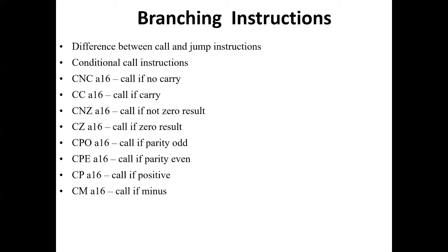Next is CPE A16. CPE is a mnemonic which stands for call if parity even. This instruction is used to branch to the subroutine whose 16-bit address is provided in the instruction only if parity flag value is 1. If parity flag value is 0, program flow continues in the main program sequentially.